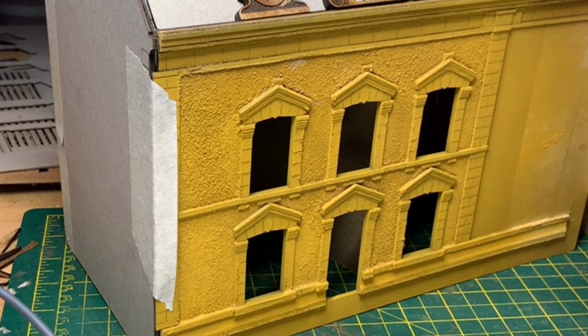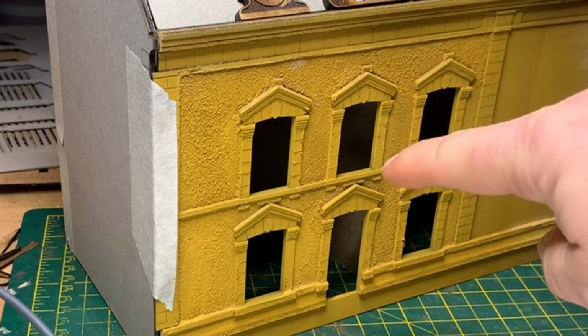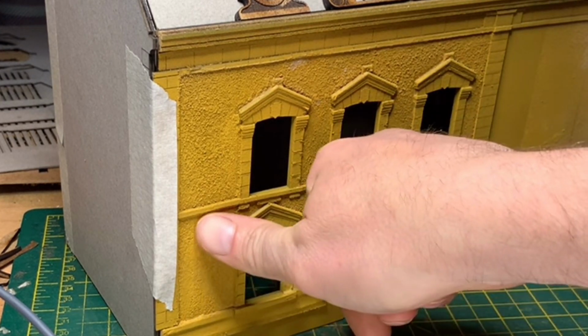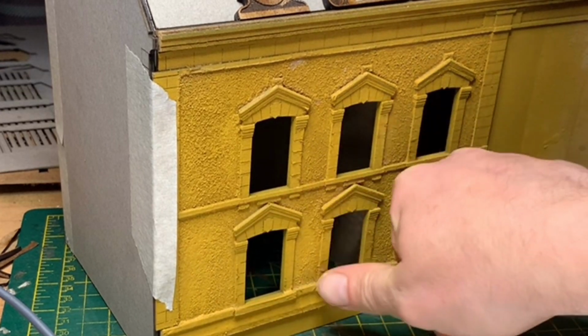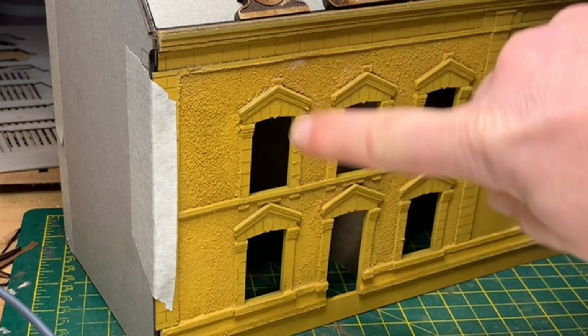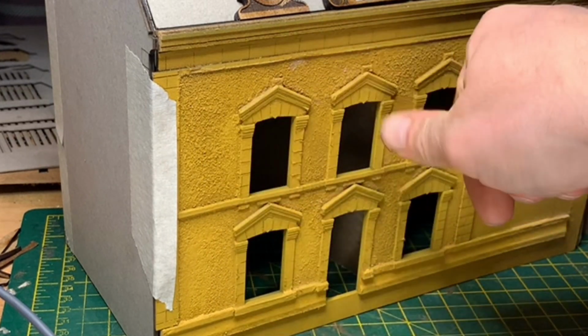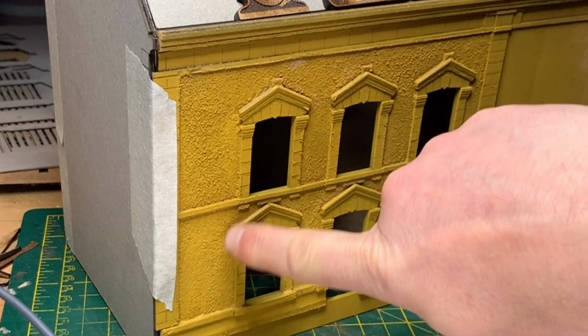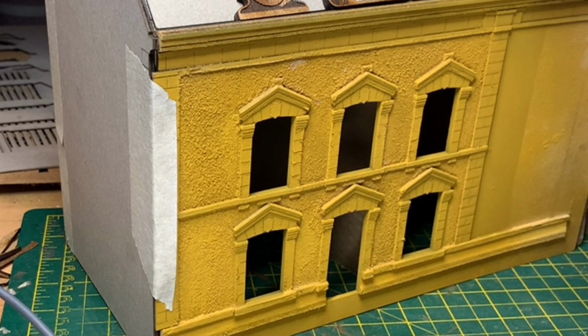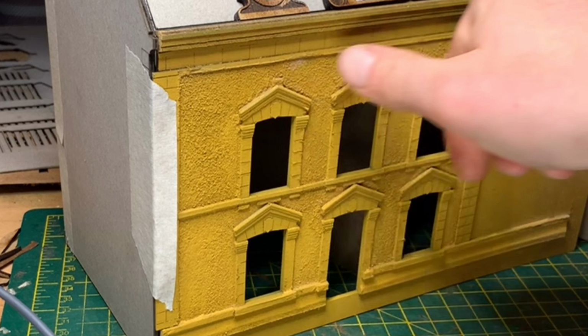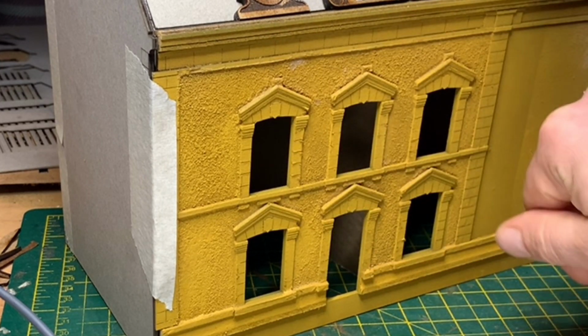So I've given the whole thing a spray of an undercoat on this side, which has tied everything together. Now I just need to sand this bit here smoother, because although this is rendered, the top part above this moulded stone is quite stippled, which I've got here, but below it is quite smooth. So I'll give that a sanding. I'll give some of the bits of decorated stone a bit of a sanding smooth.